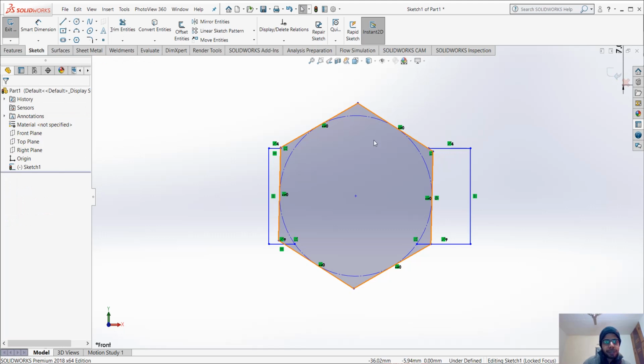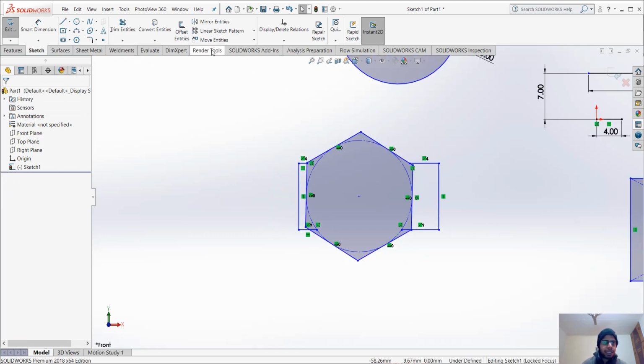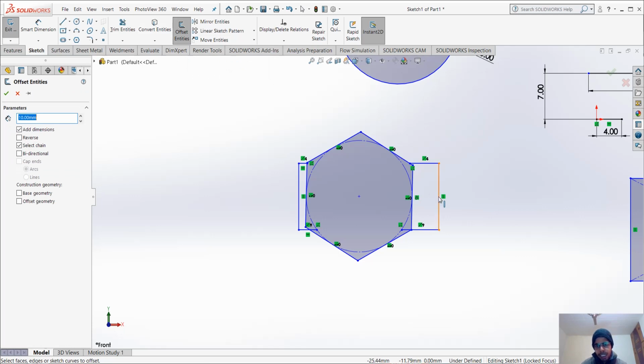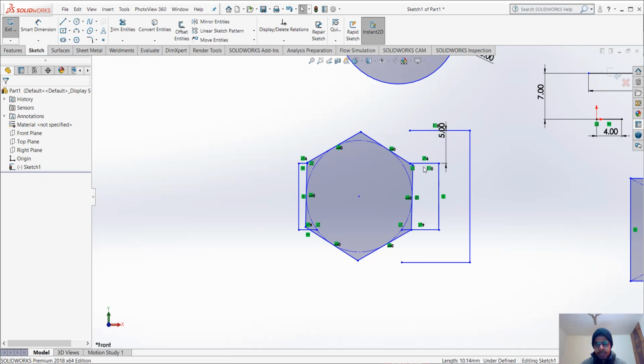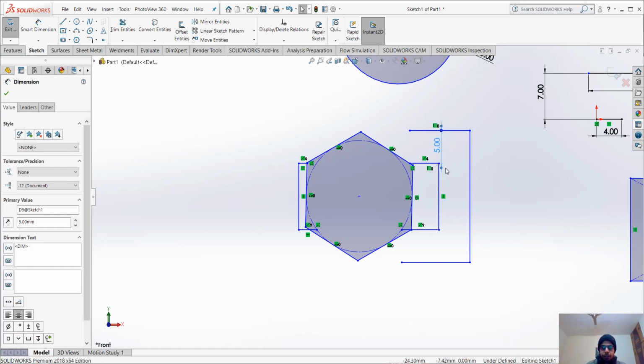And actually what I'm going to do now, let me tell you one more thing. Offset. If I want to offset this line, I click on this line, the parameter offset distance, let's suppose 5 mm, and direction this direction. It's basically selected all this, so the whole entity is offsetting. And so this and this, all the three things are offsetted by 5 units. Why is this happening?